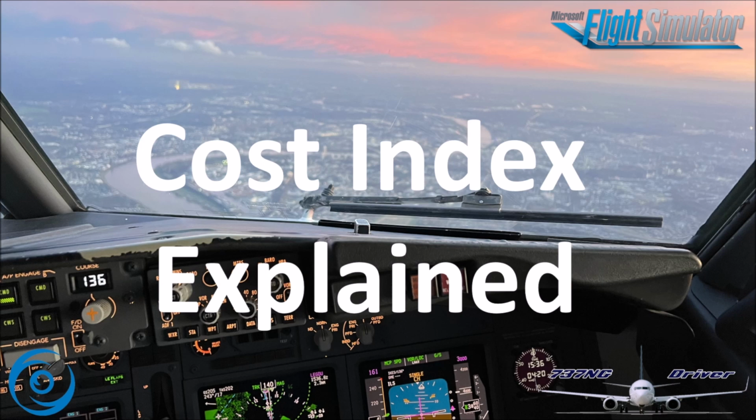And remember, from cost index 0, we had an optimum altitude of flight level 328. From the highest cost index, 9,999, we're getting level 268. And with cost index 70 over here, so our typical index, we get an optimum of flight level 327 once again. So just about in the region of the cost index 0. And the recommended level in that situation is 310.